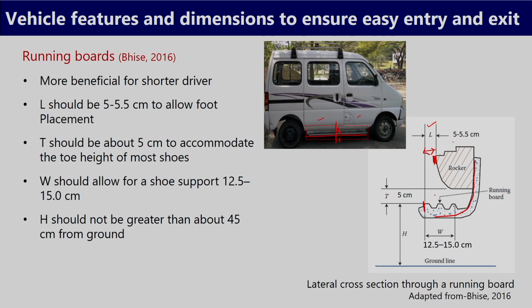Then the dimension T, that is the space available between the bottom of the rocker panel and the running board. How much should this height be? It should be 5 centimeter, so that people with higher foot height or with shoes can easily keep their foot like this.